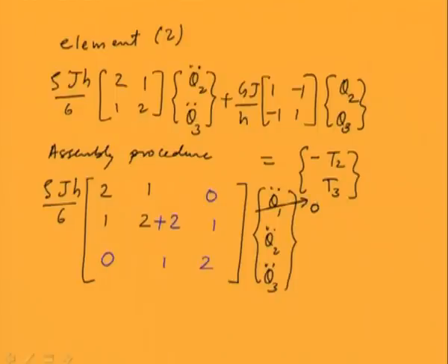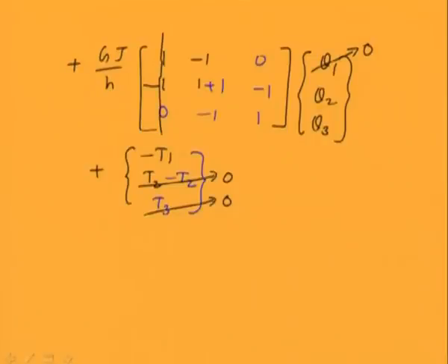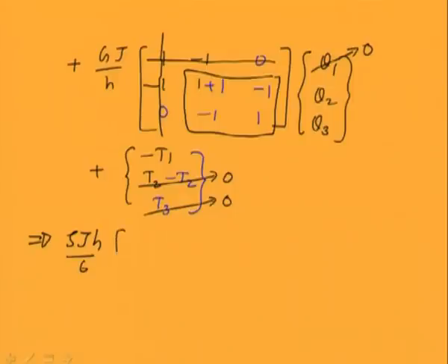So you can see that in this particular case finally we will be left with a 2 by 2 matrix, because we need to eliminate the first row and first column because they are getting multiplied by 0. So we will be left with these particular terms, and similarly in the stiffness matrix we will be left with this particular term. So after applying the boundary condition, our equation of motion is reduced to 2 by 2 size of this form.